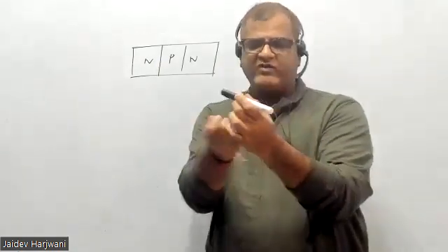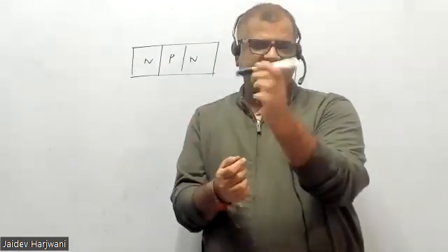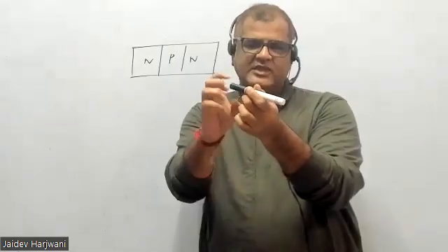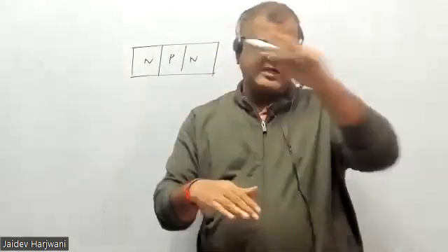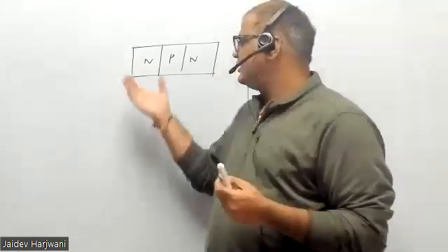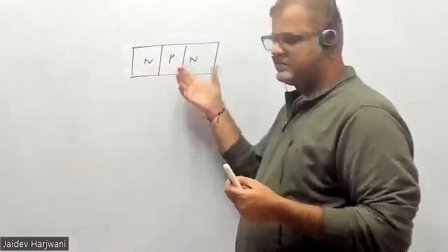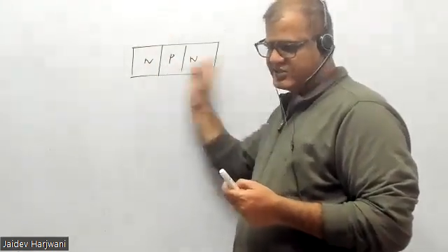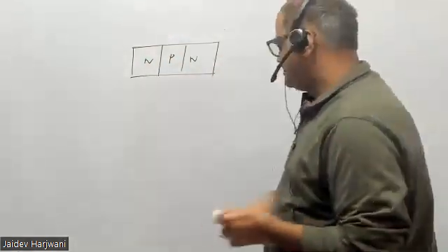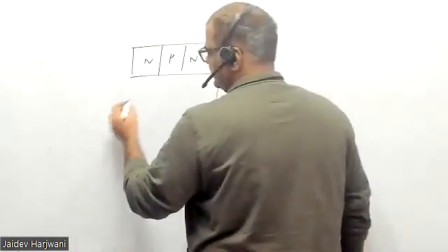If you have a bar and apply voltage, there is no current initially. If you apply voltage, that means you are shifting the Fermi levels of the two ends, and that makes the current flow. Similarly here, these have different Fermi levels, but when you make a joint, this entire section should have a single Fermi level. Let us first see the n-type material.